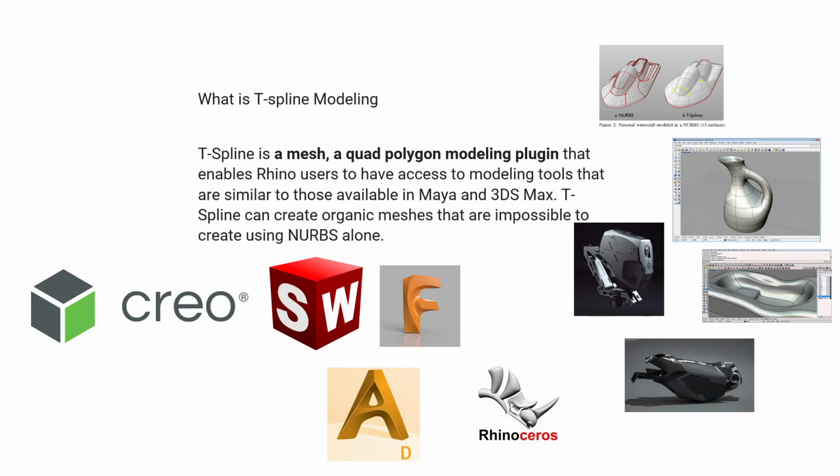You can get it dimensionally accurate within a point, but you're not going to say, oh, I'm going to draw this on the first try and it's going to be 5.25 inches wide. And if you want to go back and change it, it's hard. Where in SolidWorks, which is parametric, you key in a number and you'll get that width. So everything has a trade-off.